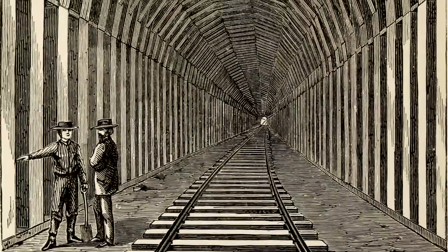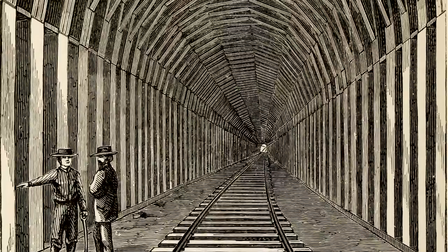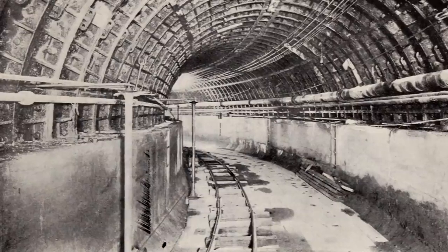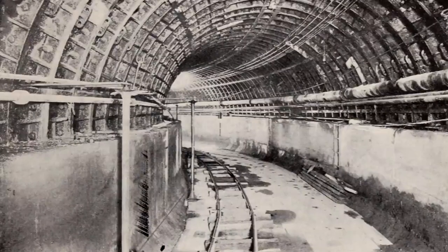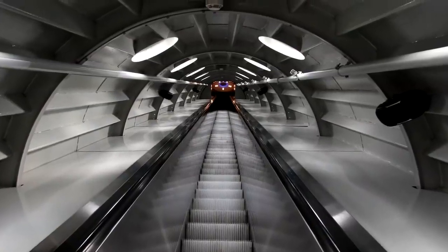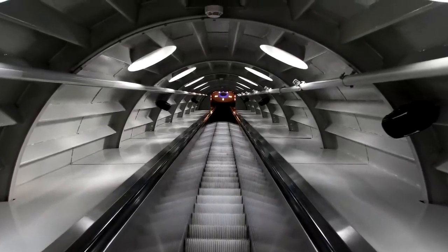So if you build a tunnel in soil, you have to replace the support you removed with some other way to transfer the load of the soil above. This is why many tunnels are lined with materials like steel or concrete, to provide support to the tunnel walls and transfer the stresses in the subsurface around the tunnel. These lining systems add a major cost to the tunnel construction.